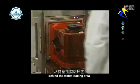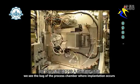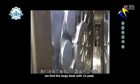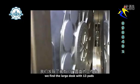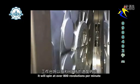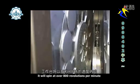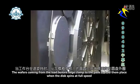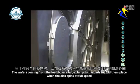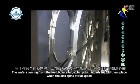Behind the wafer loading area, we see the back of the process chamber where implantation occurs. Inside, we find the large disc with 13 pads. During implantation, it will spin at over 800 revolutions per minute. The wafers, coming from the load lock, are edge clamped to the pads to hold them in place when the disc spins at full speed.